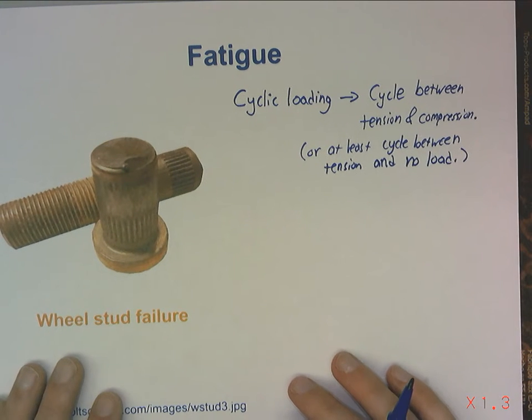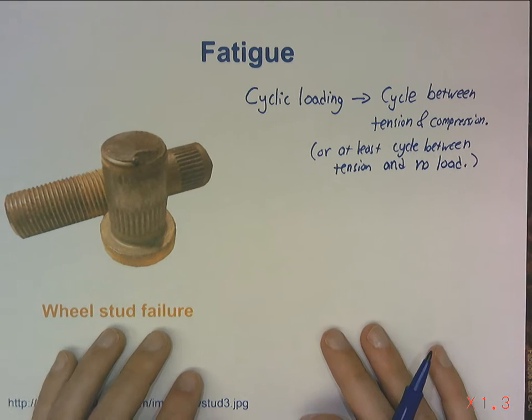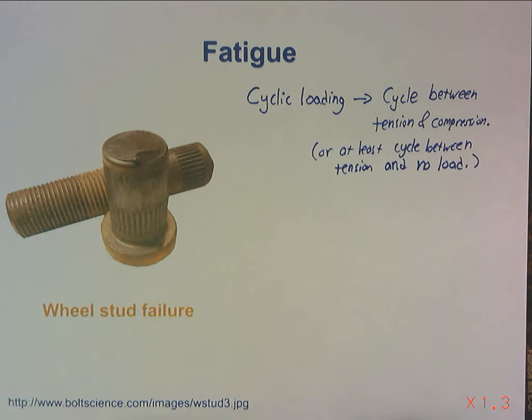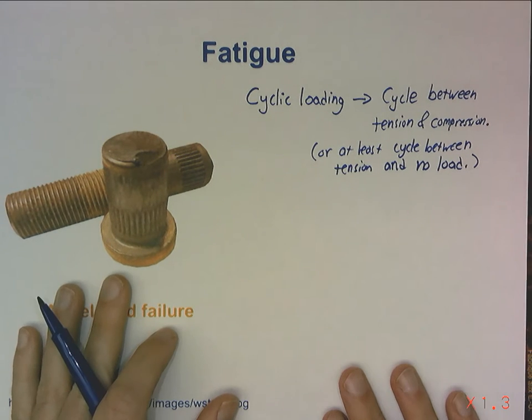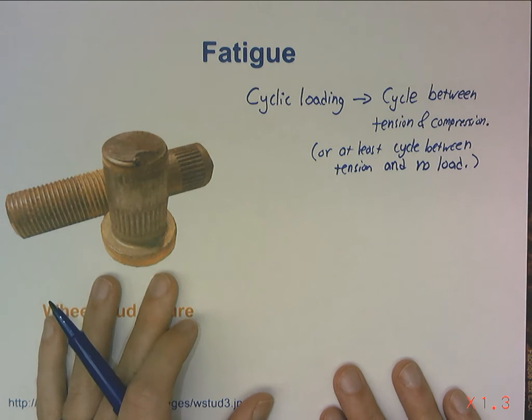So with cyclic loading, we can get a yet new type of material failure that will be called fatigue, and it's characterized by the progressive growth of a crack through the material.